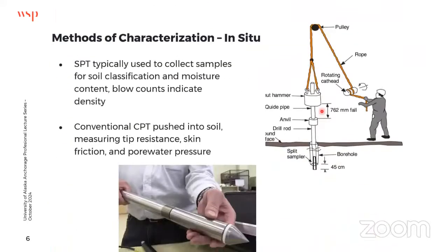All right, so again, back to kind of the old cat head rope system. All this happens now with an auto hammer. You don't see all the magic happening, but back in the day, we'd have to watch the driller make sure they only had 2 wraps around the cat head. They try to do 3, it's a lot less work, but it changes your blow count, right?